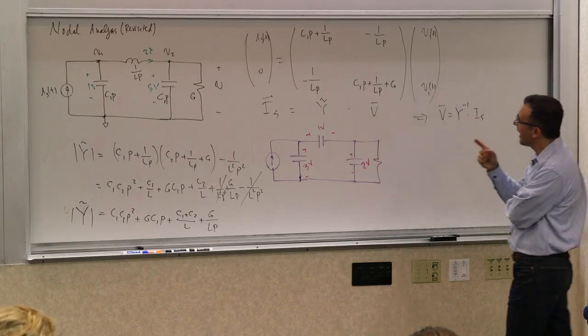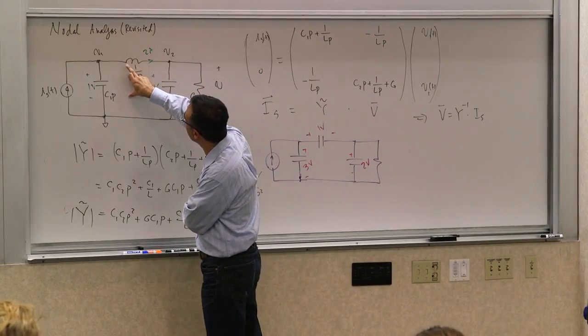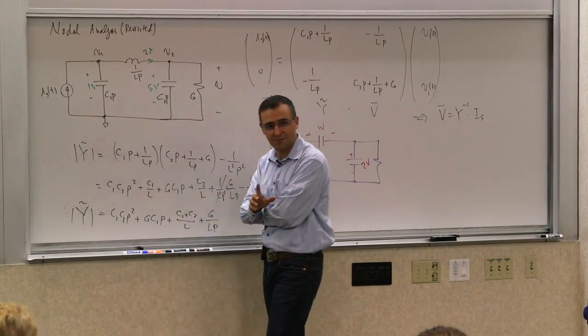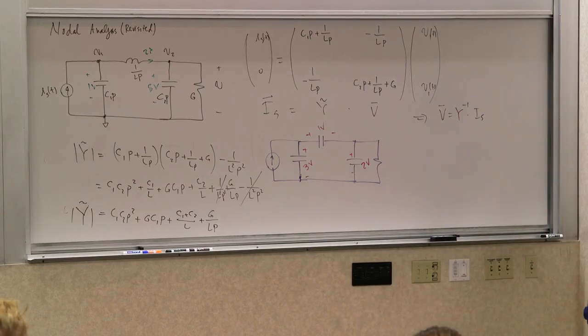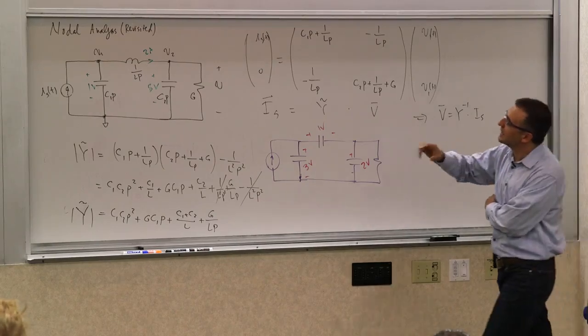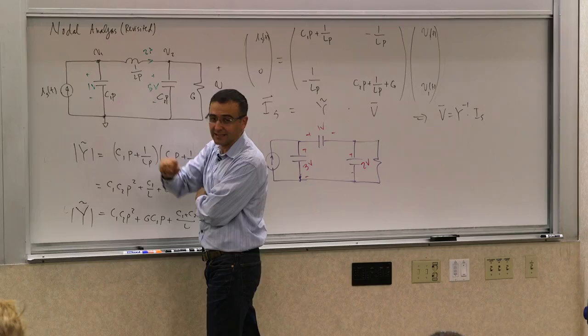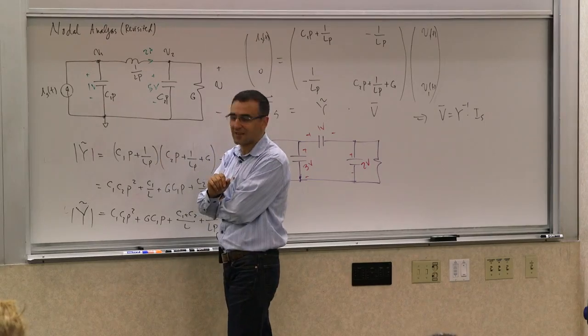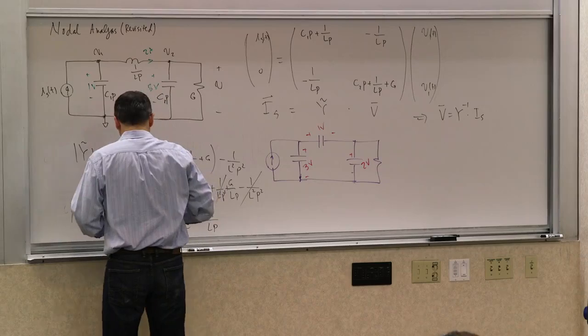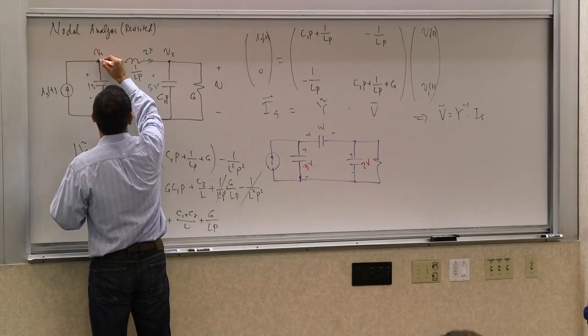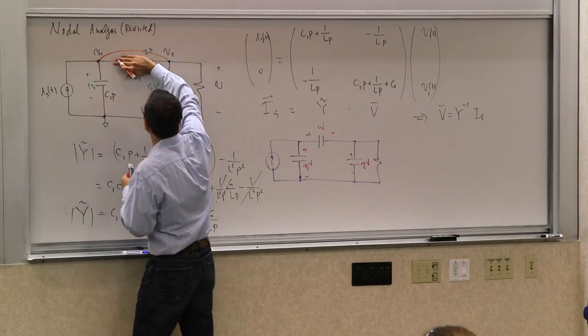But you have to be careful here. When you have the inductor and the 2 capacitors, then what happens is they're not independent of each other. So are the capacitors not independent of each other? Well, if they were connected directly, if there was no intervening connecting element. So let's say if this inductor was not here, if this was a wire,